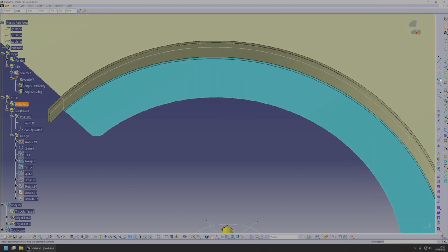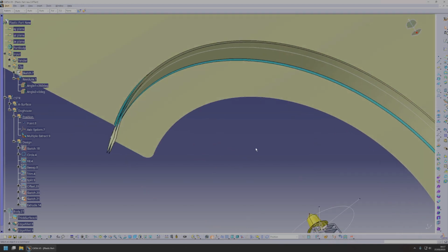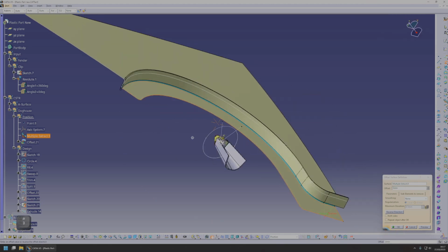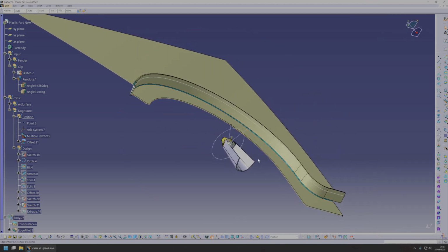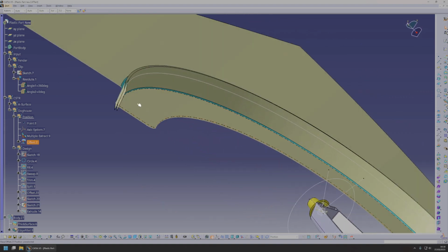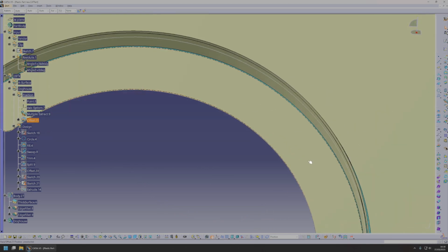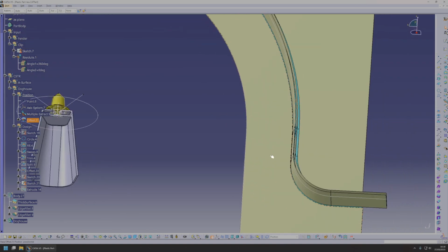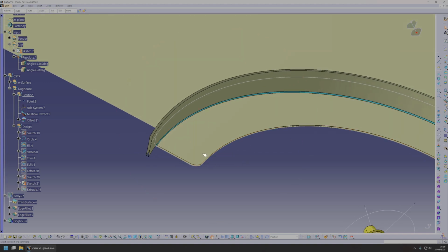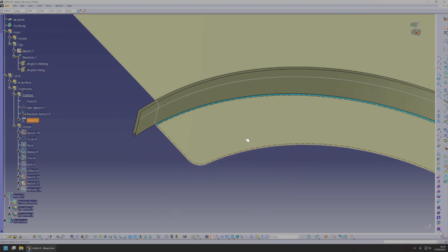To do that, I think I'm going to extract this surface. I'm going to offset it slightly. 3 mm should be fine. This is because I want the little interfaces where these doghouses, where these clips will fit into the body, to be flat, and this is not a flat surface, so I need a small bump and to create a flat surface there.